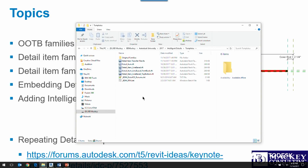This is going to sound really bizarre because there's no such thing in Revit as save as. So when I do this for all my different types of family templates, I start a new Revit family, and then I save that Revit family to a folder once I make some settings I want. And I always save that under my templates folder to a folder called original families. So I got my template folder, and underneath there I have original families. And I save those as just the RFA. I then copy that RFA to another folder and rename it RFT. So to create any sort of family template, you just rename an RFA to an RFT. You now have a family template.